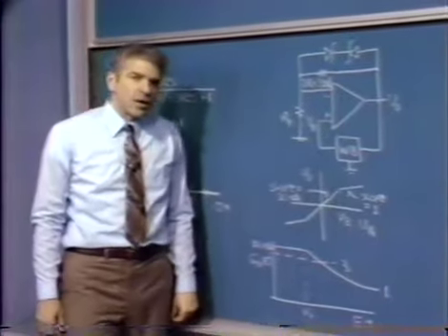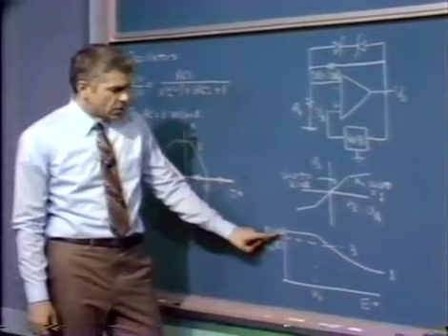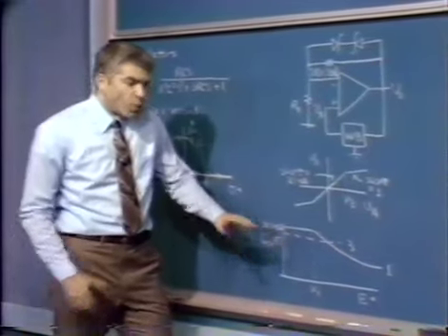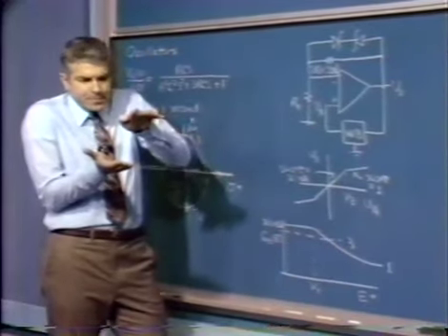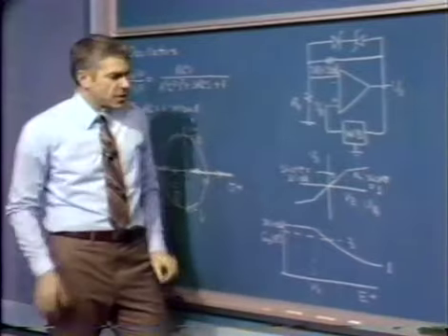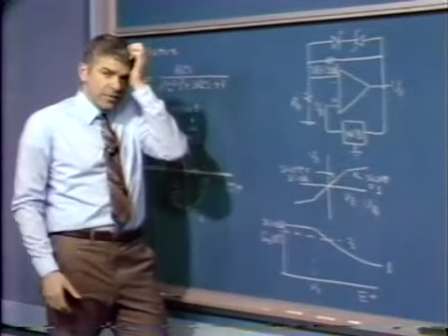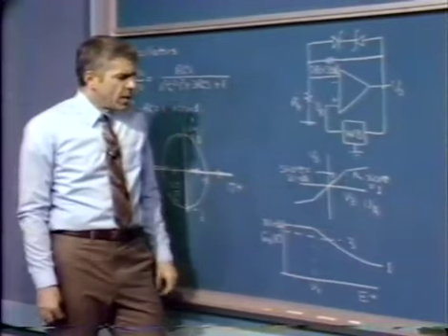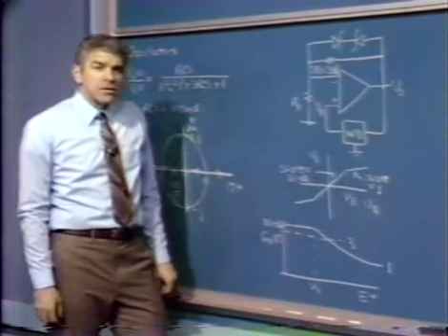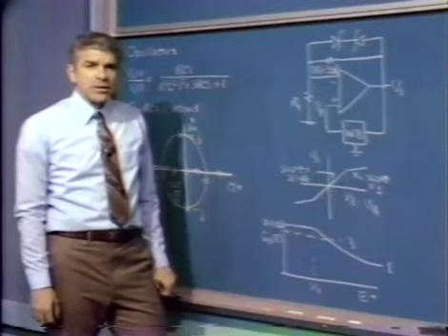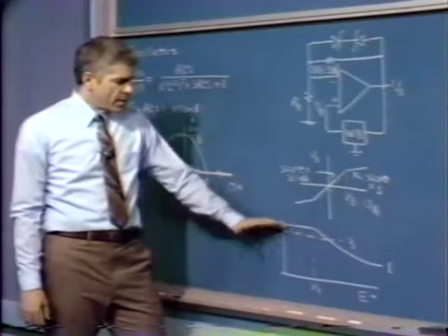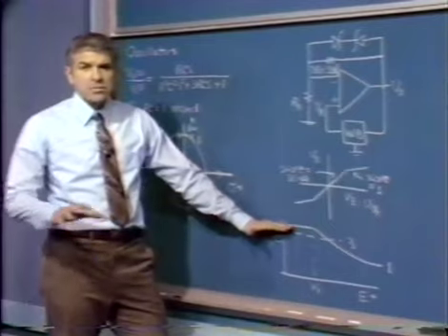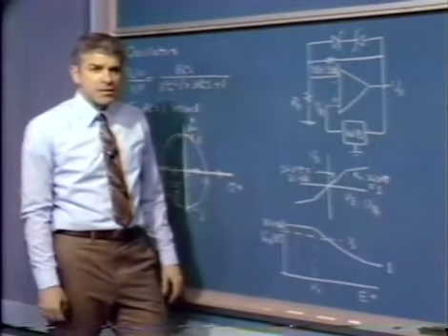We can reduce the harmonic distortion by making delta small. In that case, we just sort of edge into the limiting characteristics of the Zener diodes, get very little flattening, very small harmonic distortion. However, if we want to build a design that's relatively tolerant of inaccurate components, we have to make delta large enough to accommodate the spectrum or spread of anticipated component values.